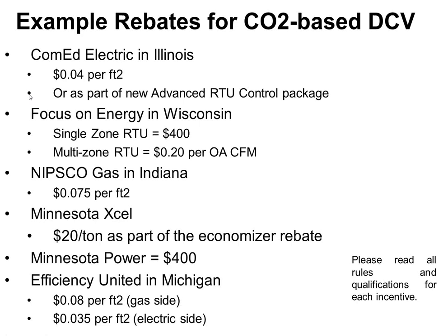Additionally, we have algorithms built into the zone damper controls to make sure we don't accidentally overcool, and we can always use the reheat to temper it back up. Reheat that I would have been running anyway had I been bringing the ventilation rate in all the time.